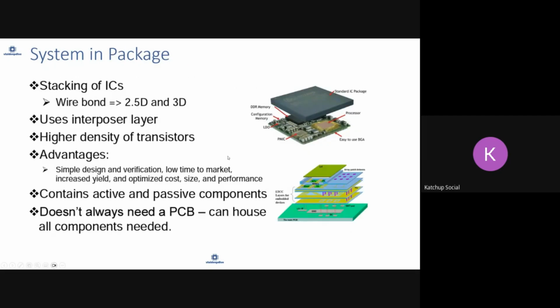Then came system in package, where you had stacking of ICs. ICs were connected together using wire bond, or later on something which we'll talk about evolved into 2.5D and 3D.